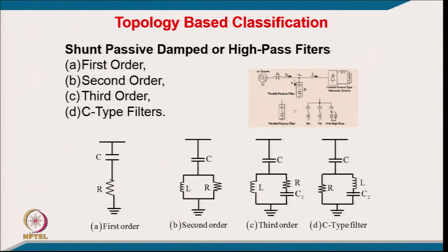Now coming to this, it is a typical example of a current fed converter where we normally use it. You have a source, a thyristor converter and this passive filter. What does the passive filter consist of, let us say for a 3-phase converter? We have 5th and 7th tuned filters and then an 11th order high pass filter. This is the same second order filter; it takes care of 11th harmonics and all higher orders above 11th, because 5th and 7th are handled separately. The 11th harmonic will flow through this and higher orders will flow through this as you see there. So, this serves the purpose of one particular harmonic and all the harmonics above that.